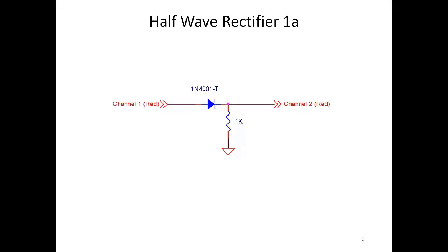Connect the 100 Hz input to the anode of the rectifier diode. Use a 1K shunt resistor and observe the output on channel 2 of the oscilloscope. Measure the peak voltages and calculate the difference for the first table.